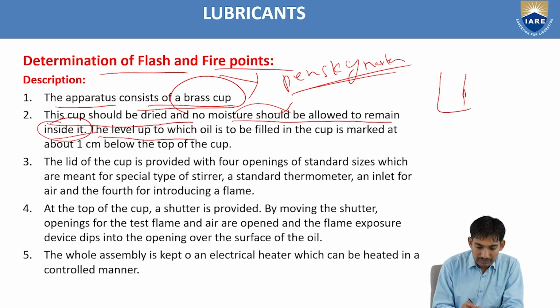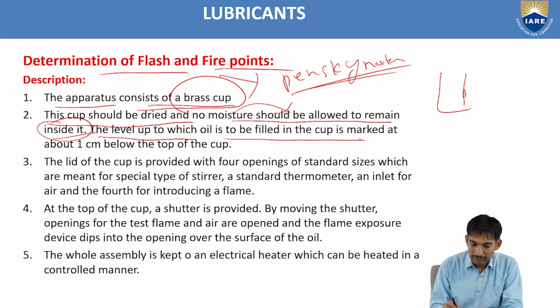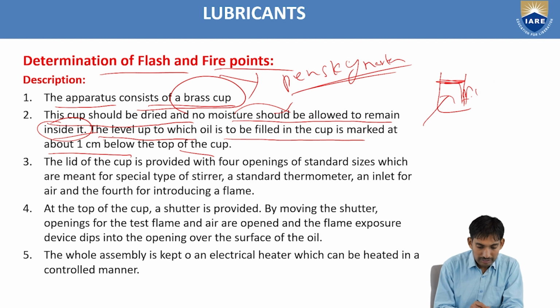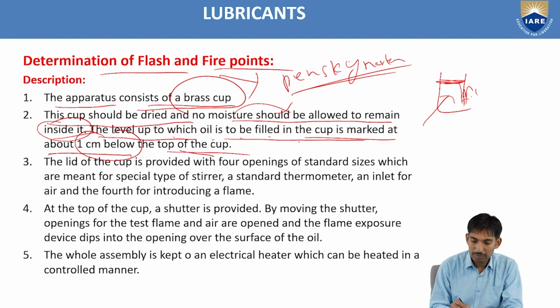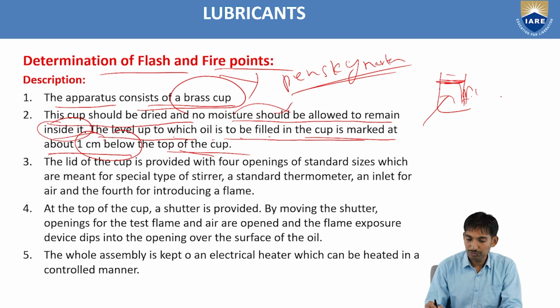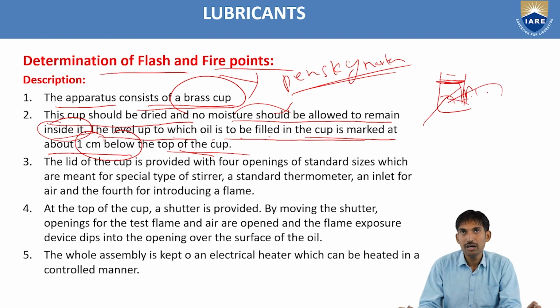The level up to which oil is to be filled in the cup is marked at about 1 centimeter below the top of the cup. From the top of the cup, 1 centimeter below, one mark is there. You have to fill the lubricating oil up to that mark.